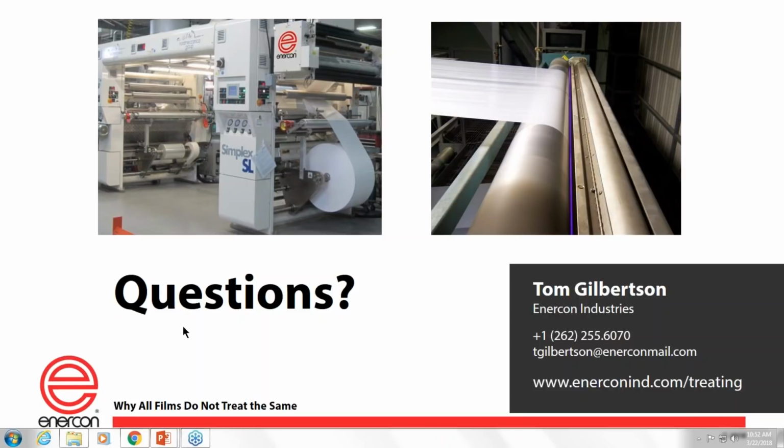If dyne levels do not guarantee adhesion, what are some of the best tests for adhesion? Well, everybody's got their own test method here, but again, depending on what the process is, so depending if it's printing or laminating, so let's pick a printing application because that's the simplest to describe on a webinar. Typically, you would use a tape test.